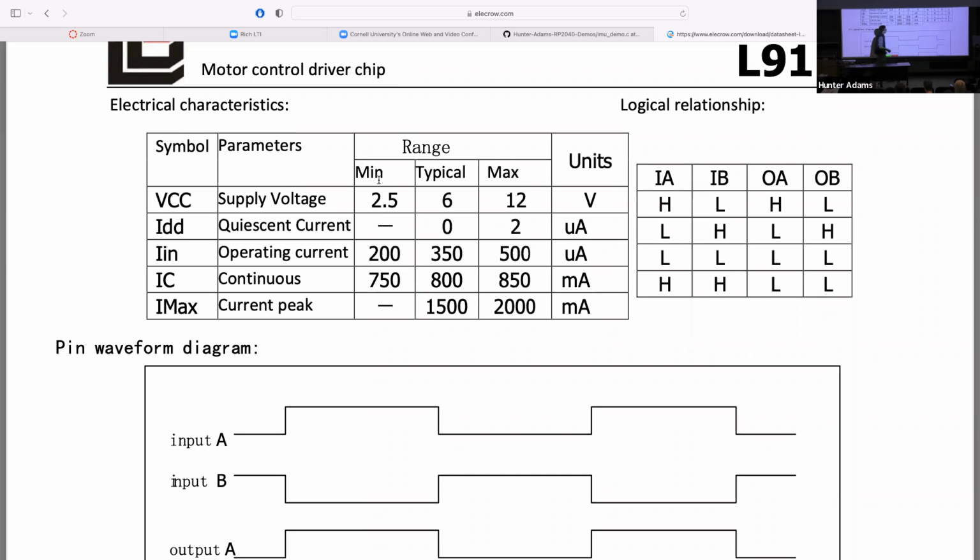If you do that, so you have two PWM outputs that look identical going into input A and input B of this motor driver, then both the inputs are always either going to be high together or low together, and the motor won't move. That is the expected behavior for this integrated circuit. But you could be sitting there with the scope, looking at the waveforms, and saying, why isn't the motor turning? It's because you're driving the two inputs together, right?